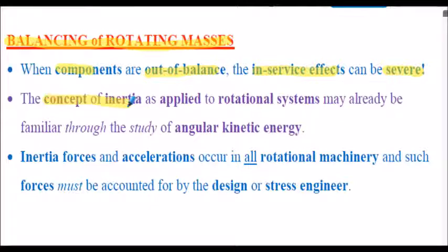The concept of inertia as applied to rotational systems is familiar to you. You may have studied before angular kinetic energy or Newton's laws of motion. We've come across the rotational masses and the inertia effects associated with them. So inertia forces and accelerations occur in all rotational machinery, and these forces have to be accounted for, and then the designer or stress engineer has to design them out, balance them out as such. And that's what we're going to do ultimately. We're going to find what the out of balance forces are in our particular situation, and we're going to try and counteract them by applying a mass at a distance within the system that we're considering. You'll see that in the examples.